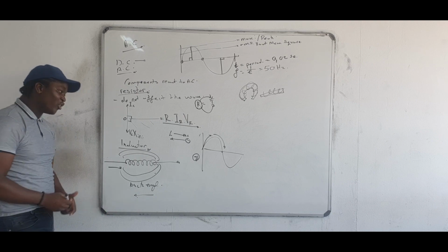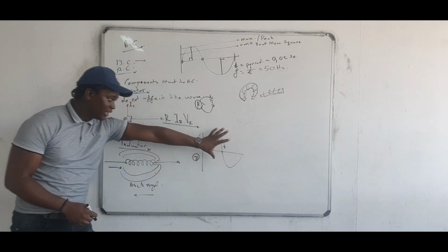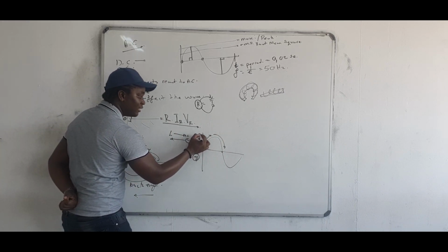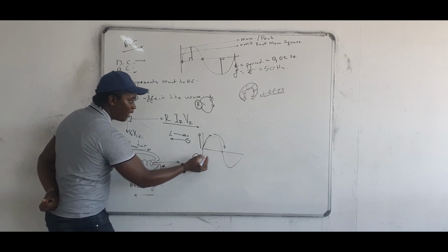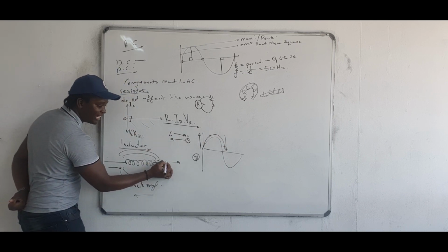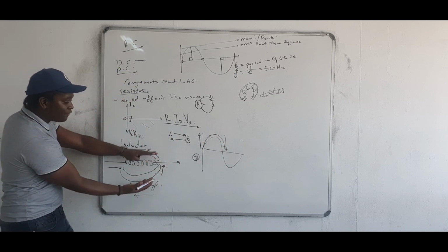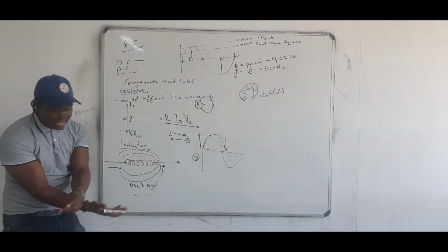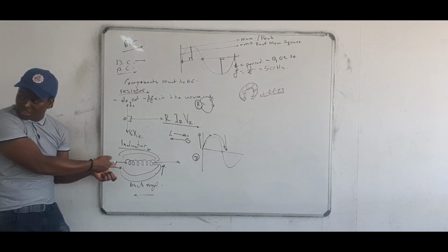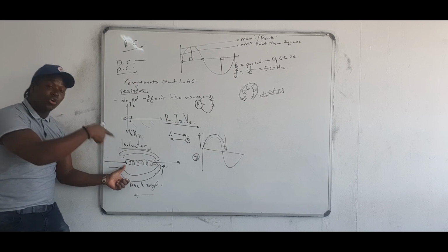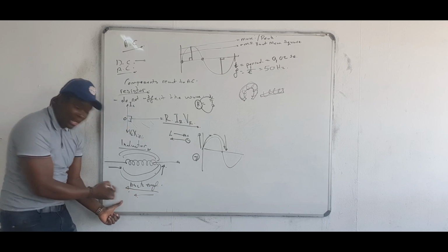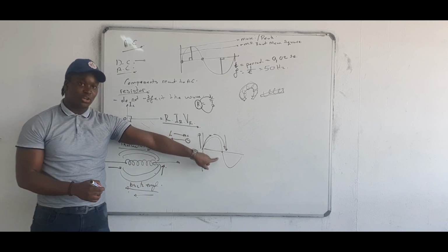Okay, so let's move over to this AC circuit now. Our current increases, so does the magnetic flux. Our current reduces back to zero, and your magnetic flux collapses on itself. That means the magnetic flux interacts with the conductor, and when it interacts with the conductor, you're going to have an EMF produced. And the EMF goes back. But we are already at zero here.